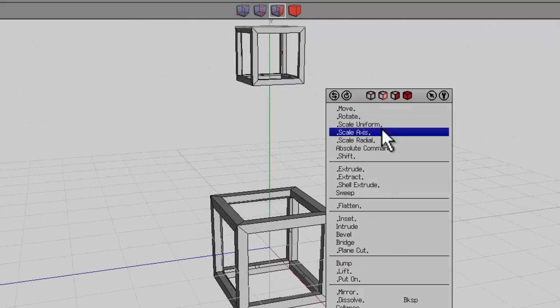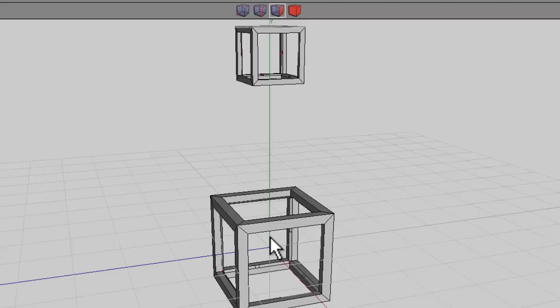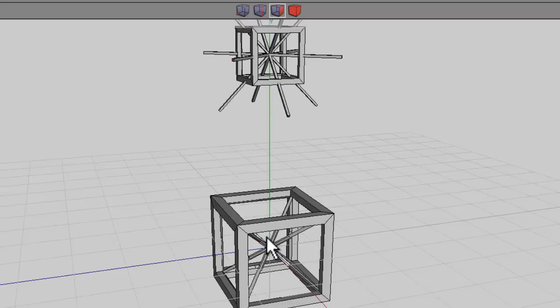Right click, I'm going to extrude and normal, and again holding the control key down, you can see I can control the level of extruding, which is handy, but there's a slight problem. This is the next problem to be aware of. Look how it's extruding. One's getting extruded more than the other because of the difference in scale. So each of these is going to have to be processed in turn, and the level of extrusion has got to be half for the one above.